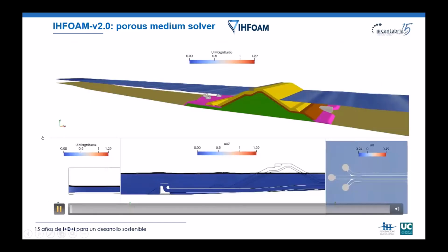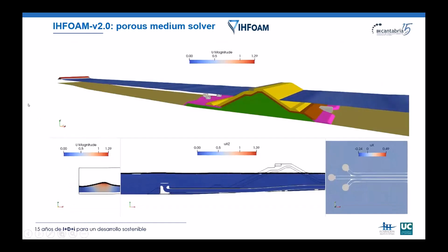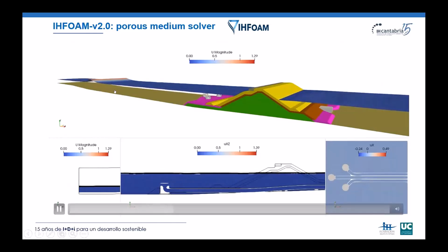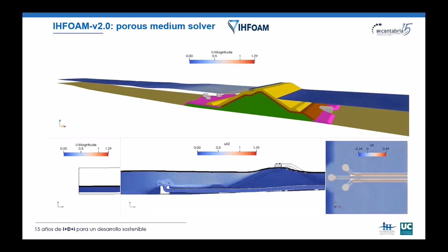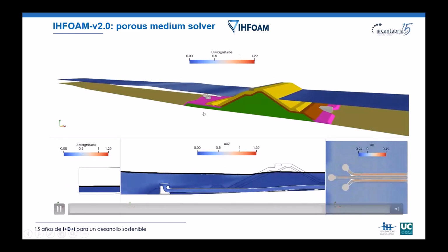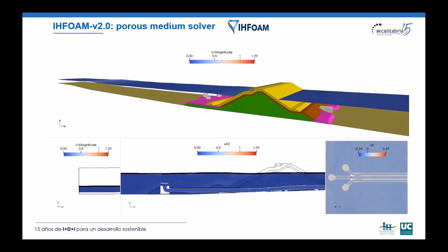The second one is another sort of application. We are generating, in this case, our wave with our dynamic boundary condition. The wave is going to be interacting with the bottom, and here we have 3 intake towers. So we're going to see this run-up event. Some of the wave is going to be reflected, some of the wave is going to be dissipated through the breakwater, and we can see even how the fluid goes through these 3 intake towers into the pipes.